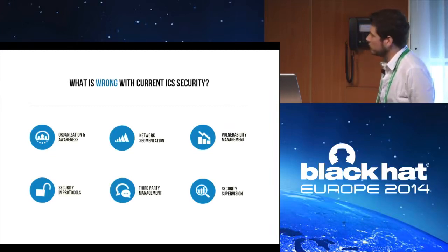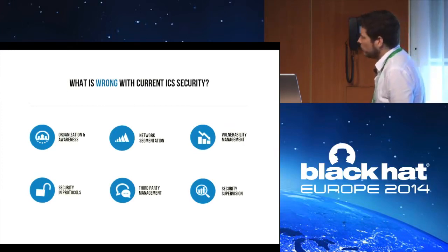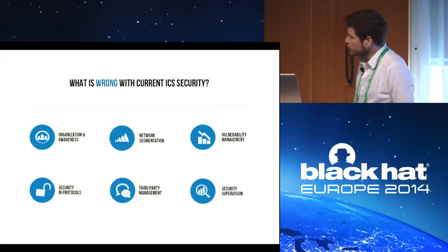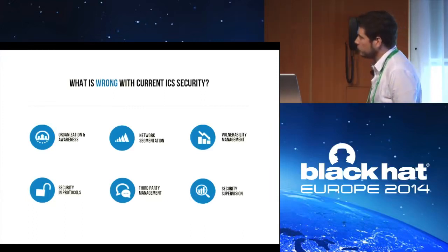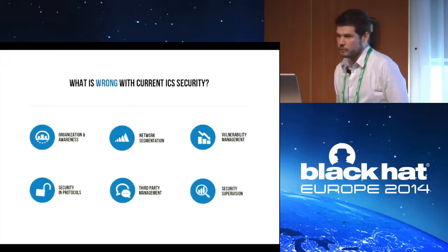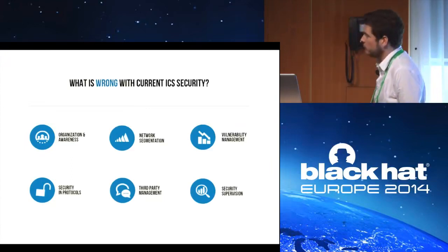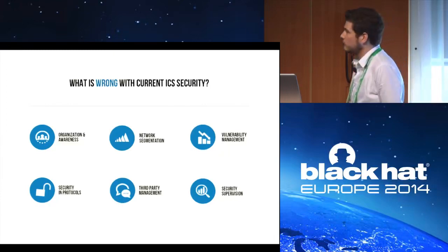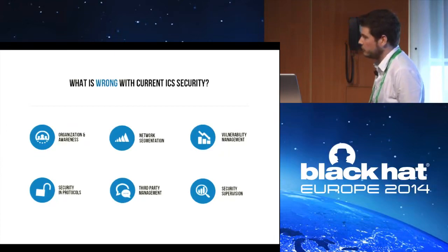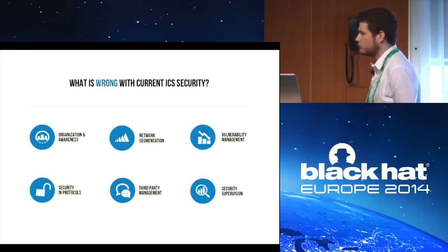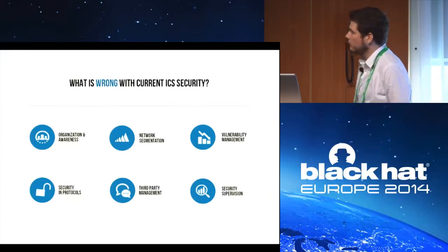Okay, so that's mostly the industrial control systems you can find in plants and factories. Let's continue with the security protocols. As we will see later with Modbus, most of the time there was no security included in the protocols. That means no authentication, clear text protocols. So once you have network access, you basically have the possibility of doing everything that you want. Combined with the fact that the network segmentation is loose, that's kind of a big deal.